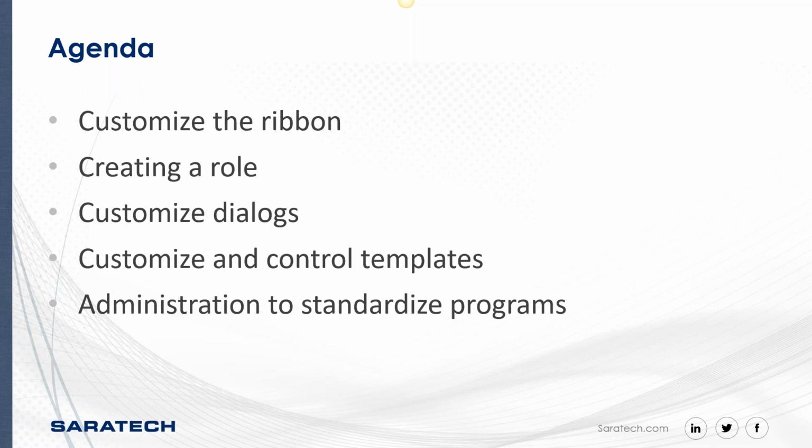But what happens if we completely blow the entire environment up and we don't have a backup? If we were to do that in the standard install of NX, now we have to reinstall NX because our standard environment, the out-of-the-box environment, is now corrupt. So that's why we create the sandbox environment and then point our custom environment variables to that location, so we can make changes as we see fit without destroying the entire installation. So with that, let's get started.